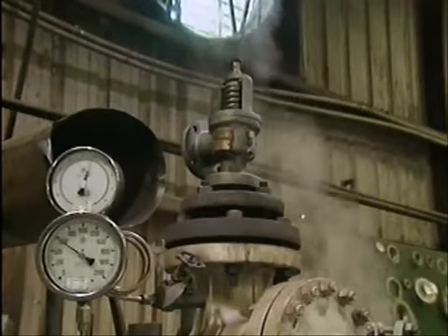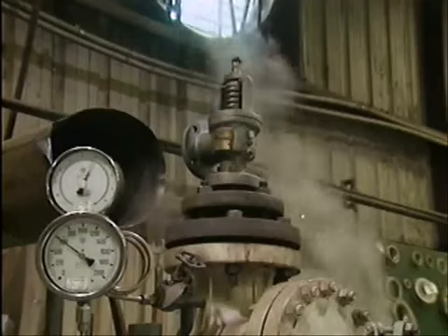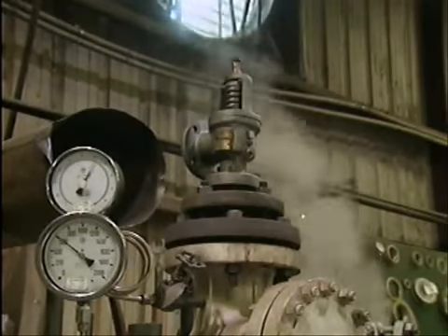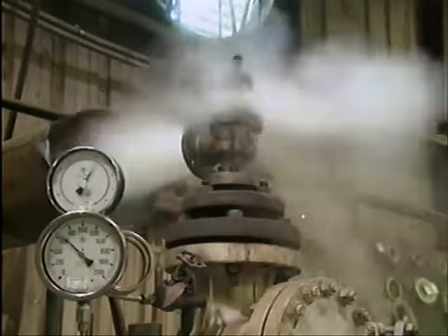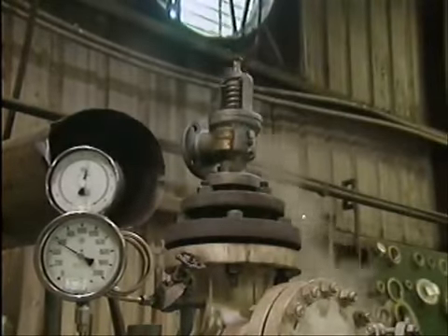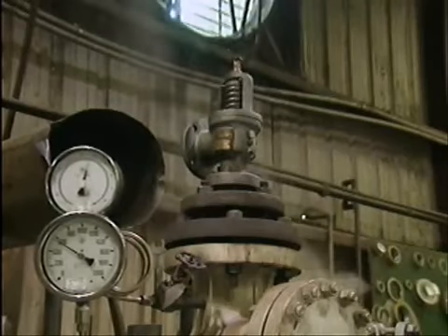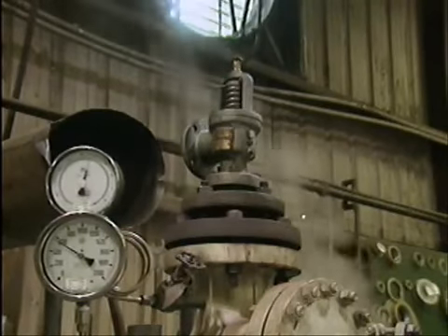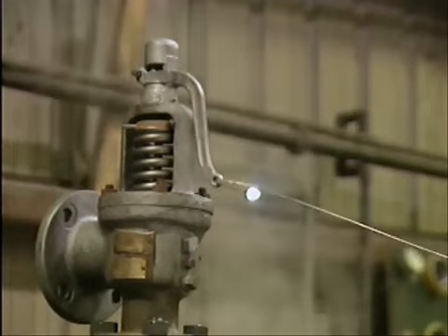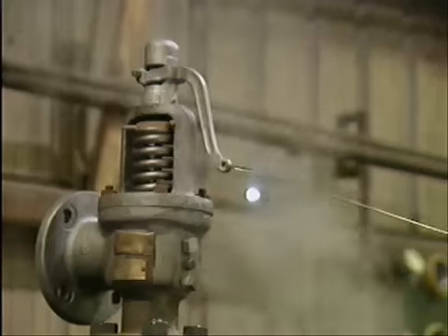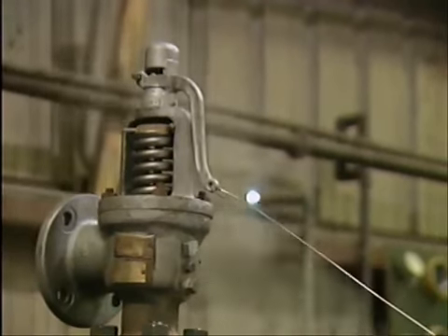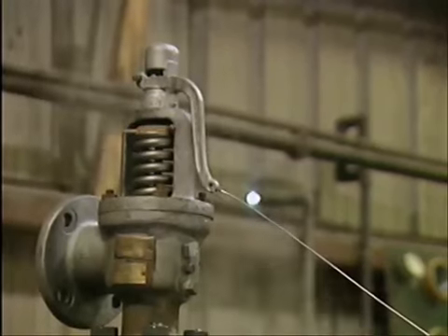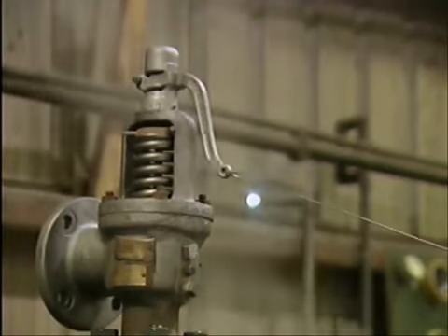An external inspection may reveal that a valve is leaking between the disc and the seat. This could occur if the valve didn't reseat correctly after the last time that it popped. Or it could be caused by foreign matter, such as ash, dirt, or rust particles trapped between the seat and the disc. In many cases, you can correct either of these two causes of leakage by manually lifting, or hand lifting, the valve. Hand lifting clears foreign matter out of the valve and gives the disc a chance to reseat